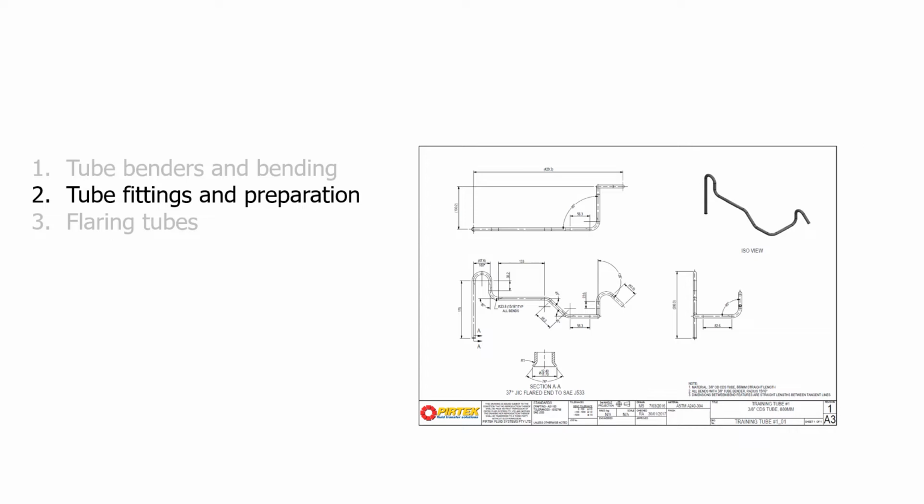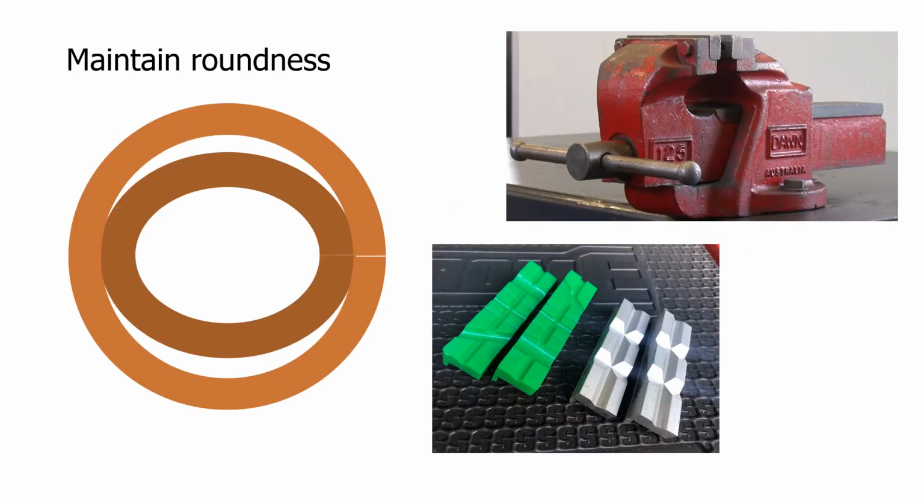Section 2, tube fittings and preparation. Again, we'll visit the parts catalogue and identify some adapters. Make sure you don't damage the tube while clamping or holding it, for example, holding it in a vise. Use vise jaws to protect the tube.